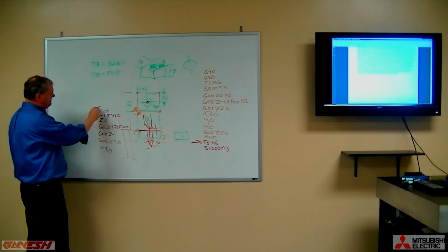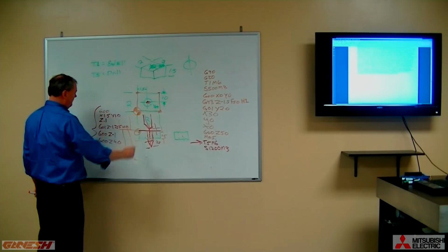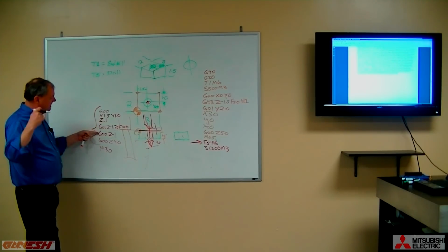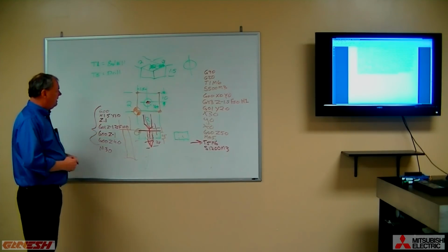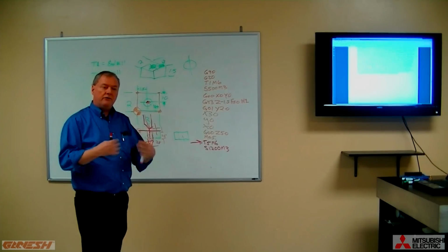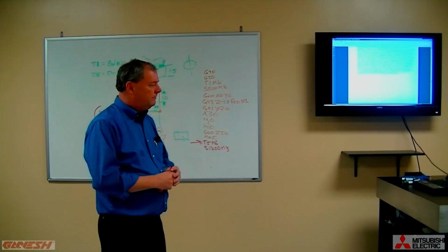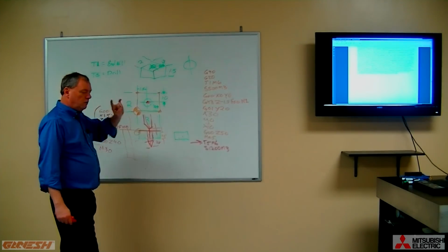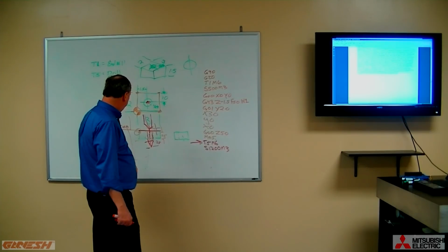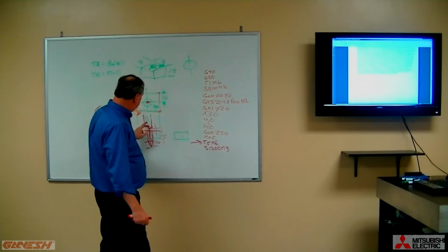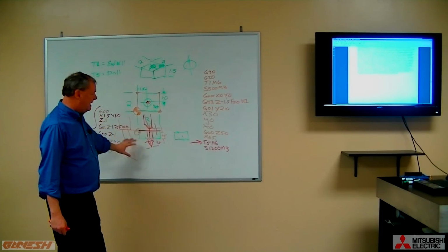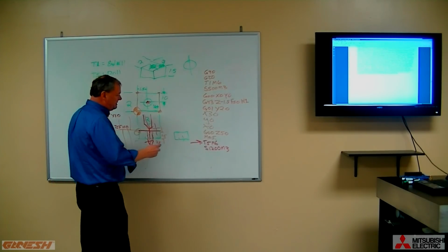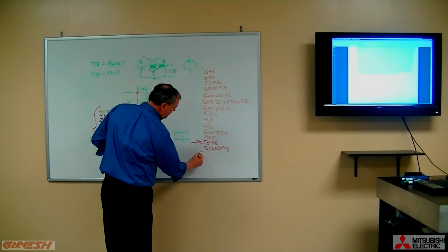All right, look at all these moves just to drill a hole. One positioning, two positioning, a feed rate, a rapid out, and another rapid. What drilling cycles do, and other single point operation cycles, is they take all of this information and combine it into one simple G-code. So to do this same motion that I've just done for you long-handed with all of these blocks, what we would do is we would simply say G81.